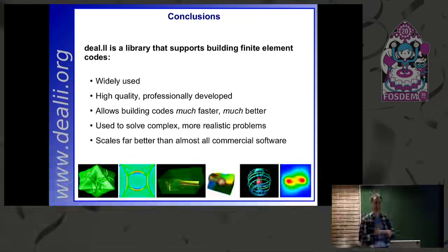And then the algorithms that you can operate on this is, refine this mesh adaptively in such a way that in those places where the solution is oscillatory, you make the mesh fine, whereas in places where the solution is nice and smooth, you keep it coarse. So that would be an algorithm. Another algorithm would be solve this linear system. All of these sorts of things.